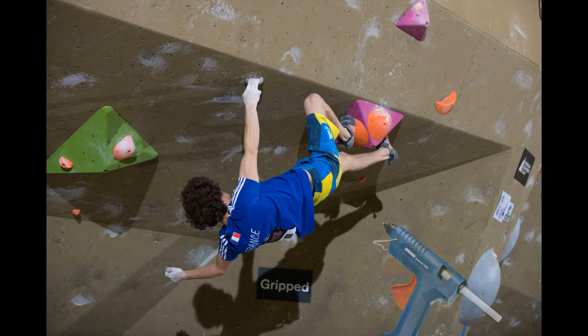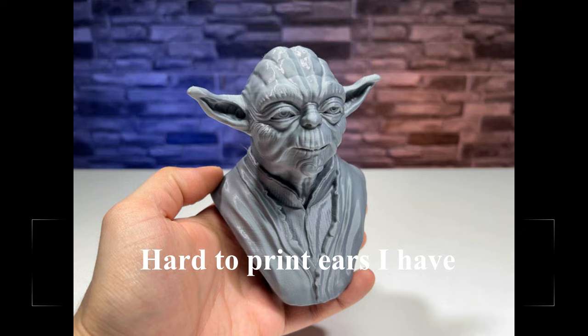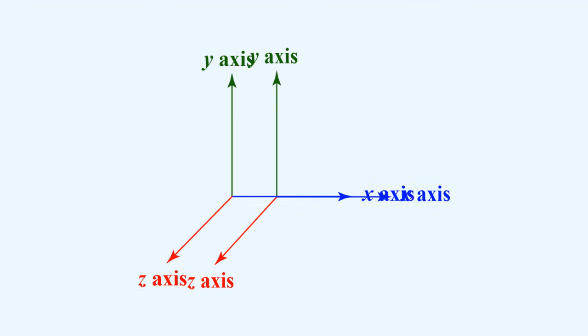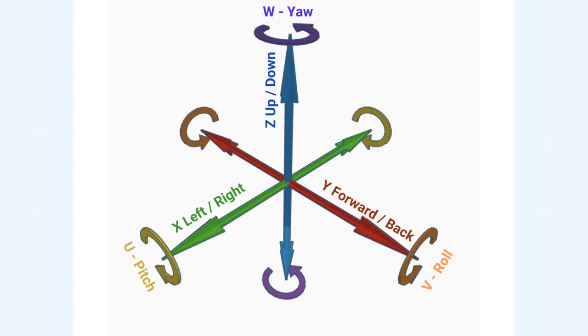This is beneficial for a couple of reasons. It helps with layer adhesion and reduces the risk of collision between the head and the printed part. However, this simplicity means that it can't handle overhangs that well. This limits the design quite significantly, as general overhangs and side features like holes tend to deviate from the design due to the physical constraints of the method, unless we use things like supports, in which case we waste material and it requires post-processing. However, by adding another axis or two, we can eliminate the need for support materials entirely.